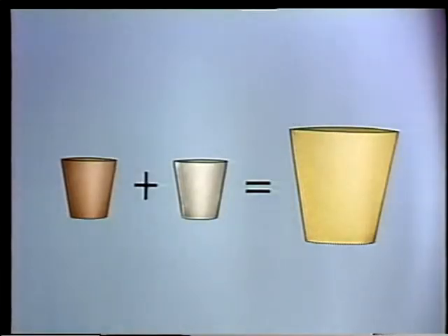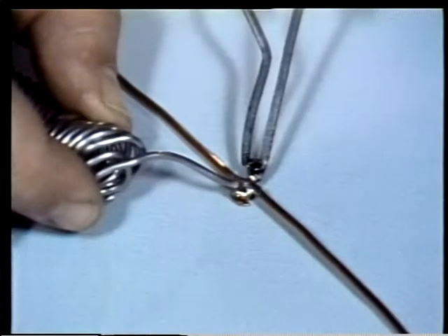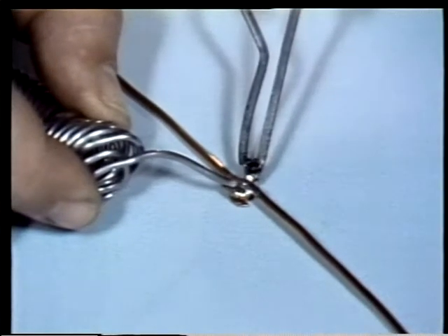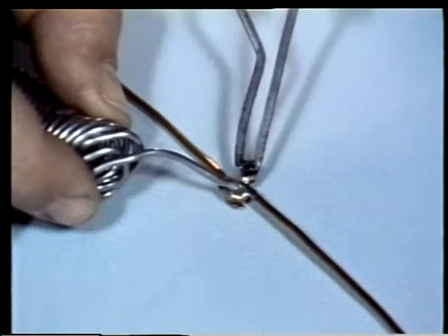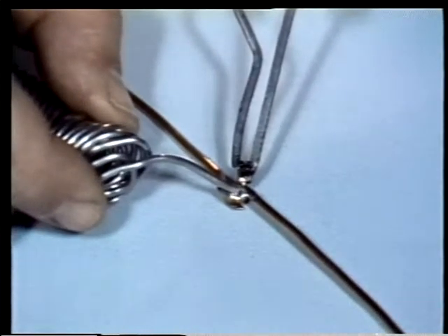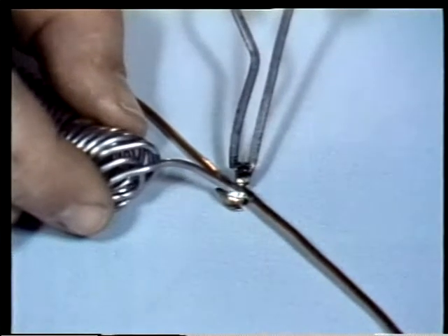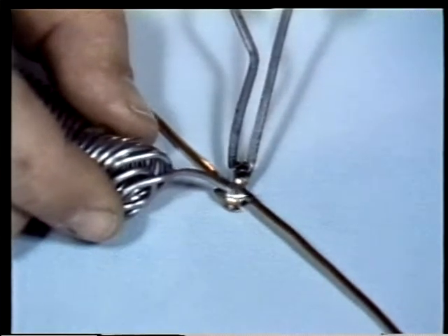Like aluminum, nickel and tin are not usually used in pure form, but are used in alloys. Both nickel and tin alloy with copper to produce alloys superior in strength and corrosion resistance. Tin is also alloyed with lead to make soft solder. Both nickel and tin are very resistant to corrosion, and both are used as plating metals to protect other base metals.